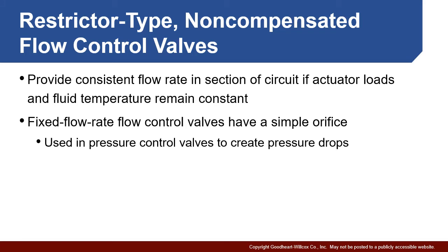The simplest type of flow control valve is, as I said, a restrictor type, and if they just basically reduce the size of the opening, they're non-compensated. Essentially, they just have a simple orifice. In some cases, you can actually just mount a plate with a hole in it, and it's going to cause a certain pressure drop and reduce the flow. But keep in mind, as I mentioned, things like viscosity, pressure, etc. can change. And when those do change, with these non-compensated ones, you're going to get a different flow.